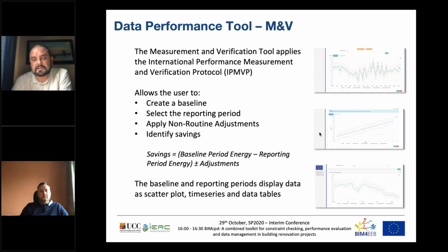In addition to that, the user can also apply non-routine adjustments. So if the building was, say, 50 or 60% in usage during the baseline, and that changed during the reporting period, they could apply non-routine adjustments to that data. And that's obviously M&V practitioner expertise.